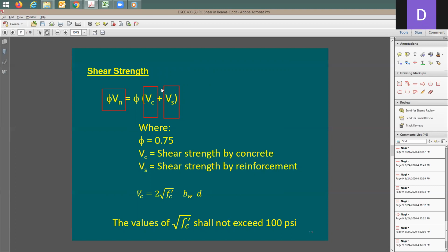Ties, right? Yeah, from the ties. Because in beams, the shear strength is coming from the ties. It doesn't come from the bottom or top reinforcement. The phi factor is just one value. You see here what it says, 0.75. Nice. So I'm not going to have a graph. I don't have to find out the strain in reinforcing. Just phi factor for shear is going to be 0.75.